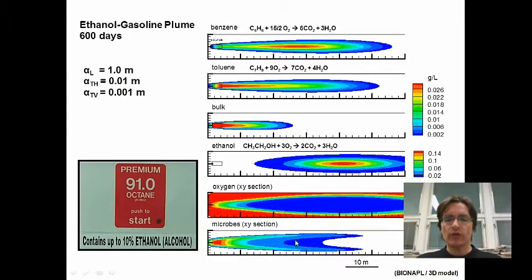And we have the microbial growth, again, highest near the source zone, where we have this continuous, slowly dissolving source zone, as well as a continual replenishment of oxygen from up gradient. So we have a good replenishment of oxygen here, a long-term source of organics, so we have some strong microbial growth, and then growth along the fringes again. Again, good dispersion characteristics here, giving us a good simulation.